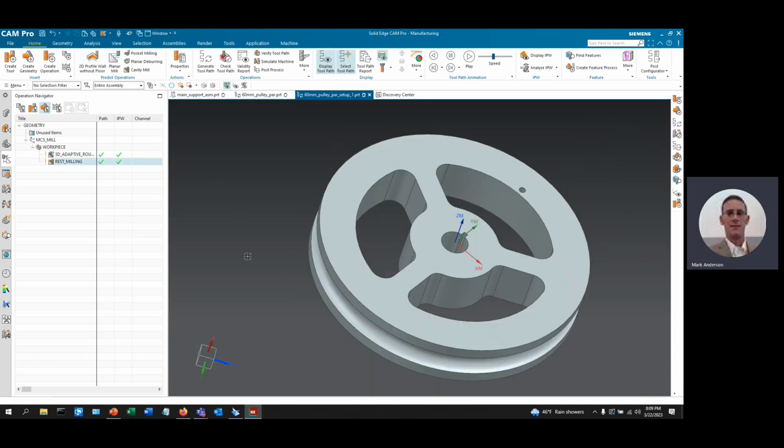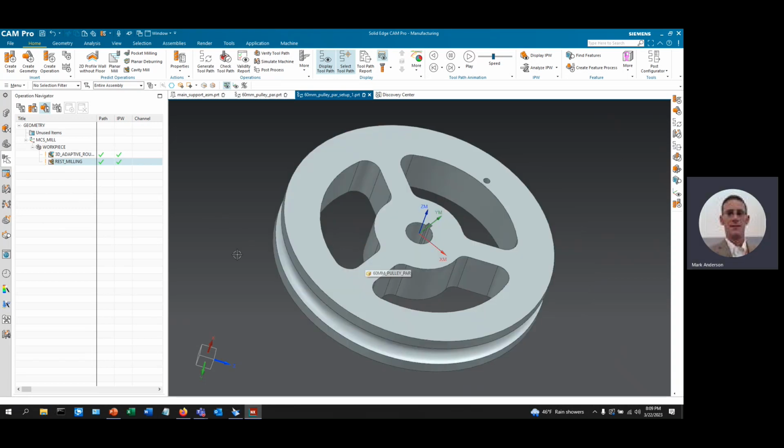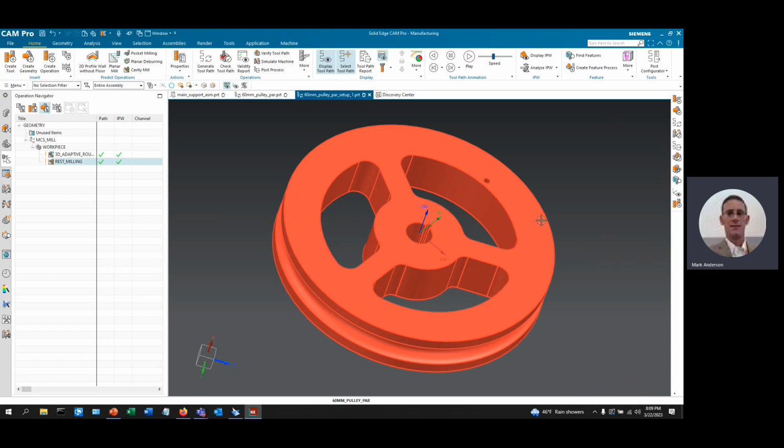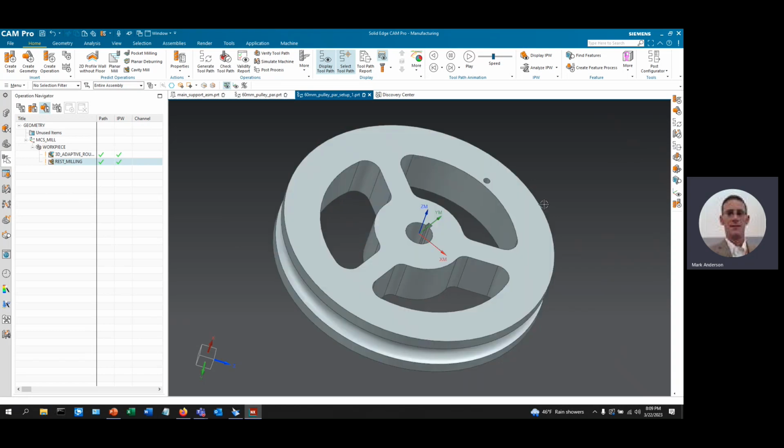So now we will go into hole making, because hole making is much different than other softwares. The CamPro software is also volumetric when it looks at the holes. It is looking at these features as an entire feature and not just a point that you're telling it to put a specific tool in. So a couple caveats to hole making. You never have to specify a center line. If you're doing 3+2 machining and this were to be on the side of the part, the tool is always going to go center line of tool, center line of feature, and the post processor is going to work out the rotations. So it's very intuitive when it comes to how it looks at holes, how it rotates things around for multi-axis machining, whether that be 3+2 or full 5, and how it outputs.